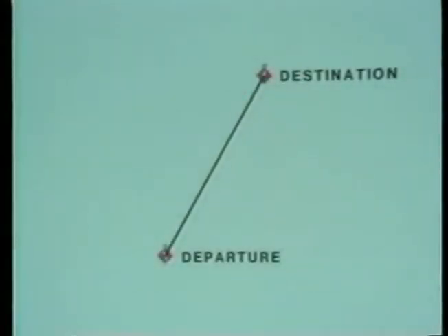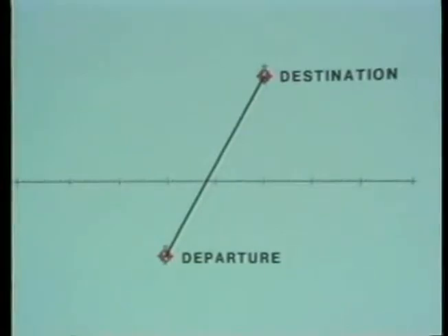If your course does not cross a line of longitude, you can use a line of latitude for the measurement. The small north-south scales are used instead of the larger east-west scales. In this example, the true course is 30 degrees.